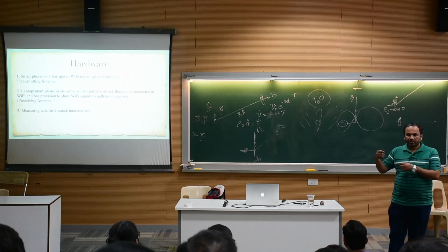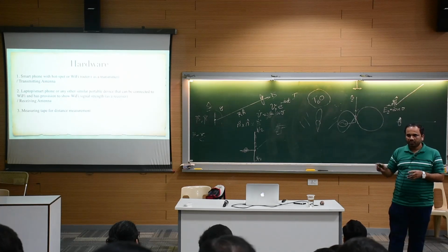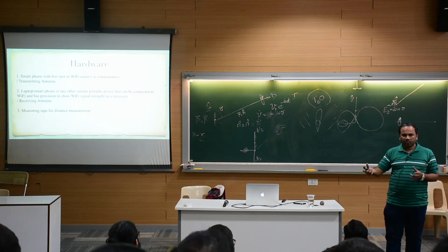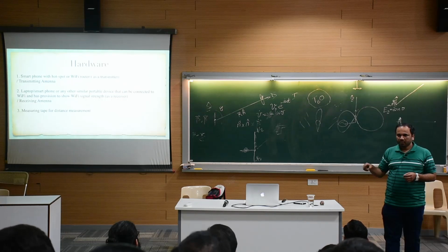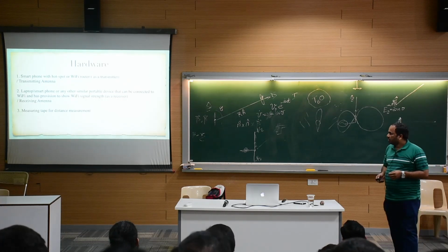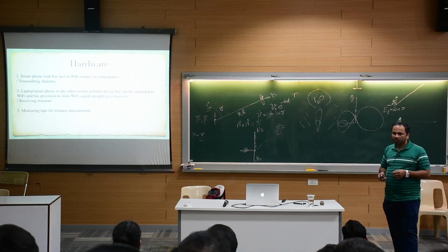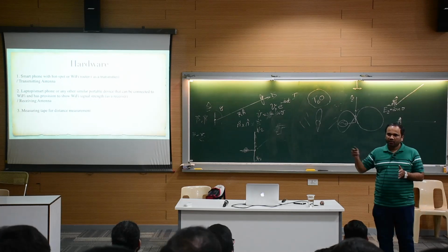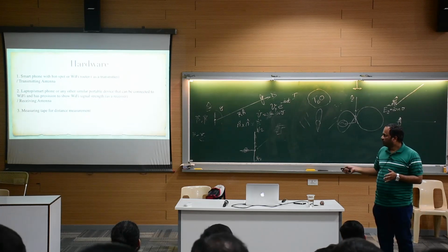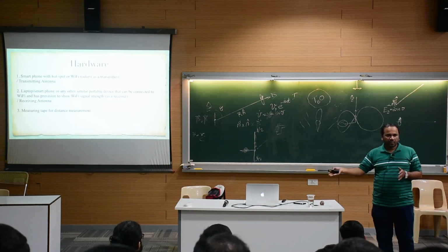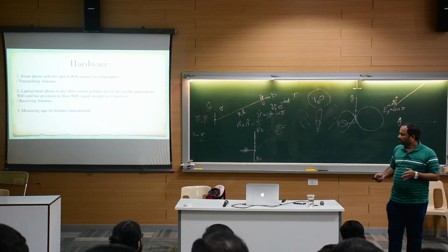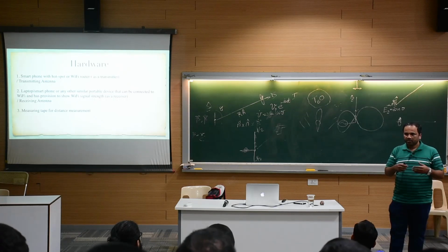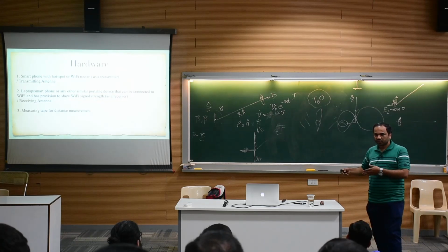If you're measuring the power on a laptop, it will be in dBm, and if you're using the other set of instruments, like a Yagi-Uda or dipole antenna, then you should be able to measure in current, in microampere. We need one or 2 smartphones: one at the transmitter side, and the second at the receiver side. If you're using a laptop, it can be used at the receiving end. And you need a measuring tape to measure the distance. These are the hardware you need for this experiment.